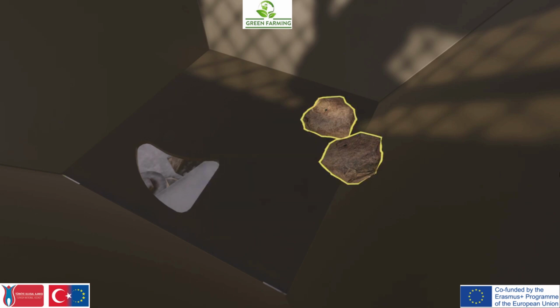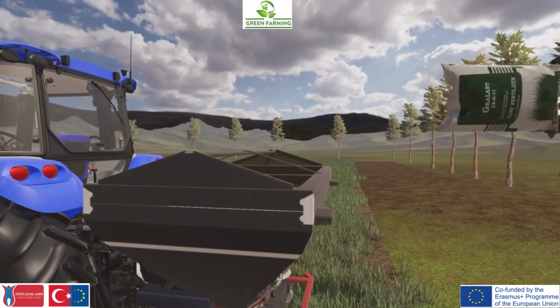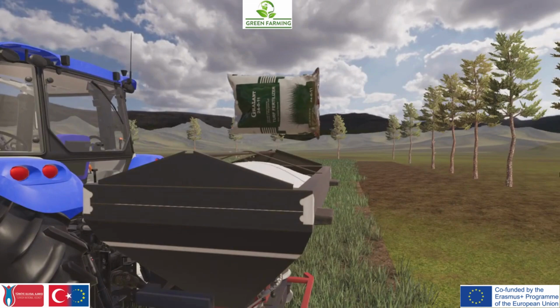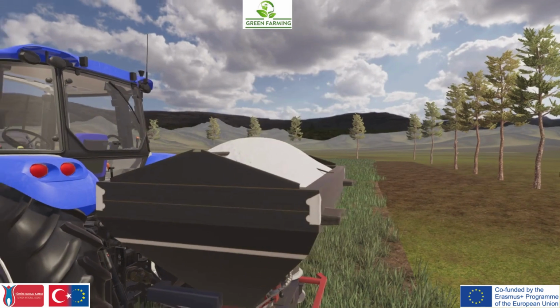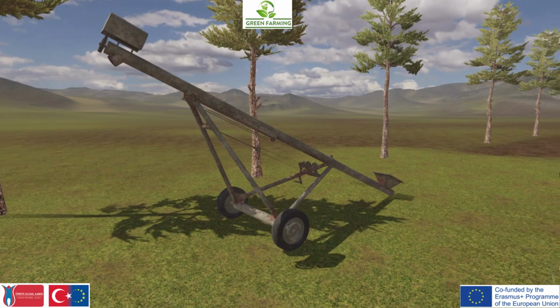Ensure there are no stones or other foreign objects in the hopper. Ensure the fertilizer flow covers are closed. Fill the machine with fertilizer using bags or sacks. A universal feed auger can save time and labor.